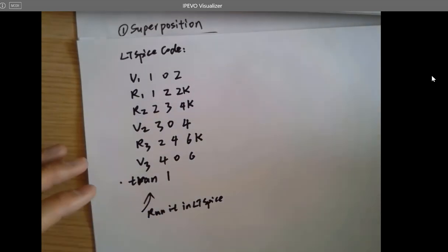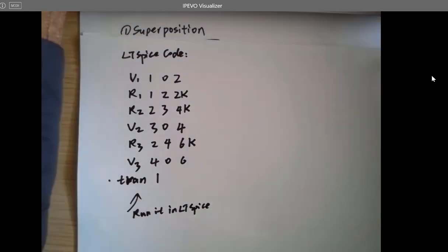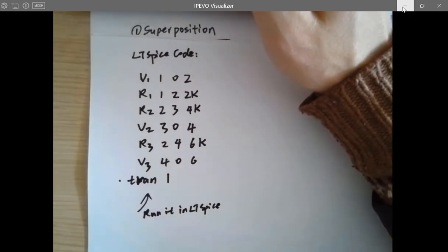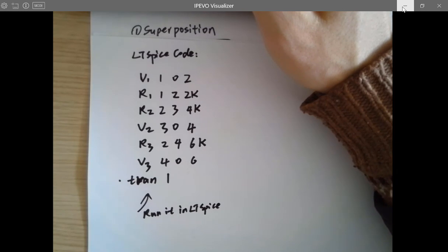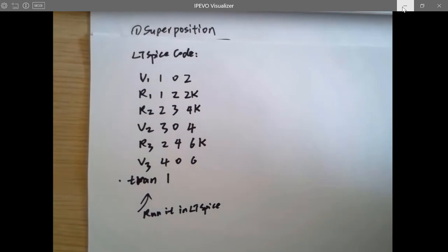So how many different ways can you run a code in LT-SPICE? Just to remember that. I think it's 2. What is the third one? So the first one, you can run a TXT file. The second one, you can directly do a .op and put all the SPICE code into LT-SPICE. And the third one, you can simulate it not using a code. Just use a schematic. Just put the symbols into LT-SPICE and run it, right? So 3 different ways.